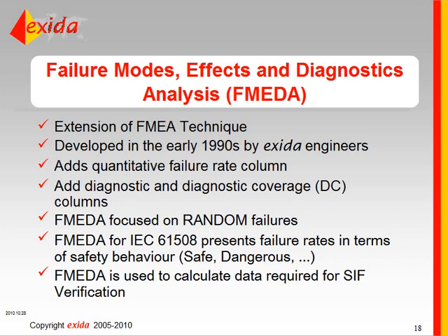It's focused on assuming that the design is correct, the parts are operating within their correct ranges, and there's still an expected failure rate of components even when they're not overstressed and when they're used properly. And those are considered random failures because they occur at random times. It's during the useful life of the component, too. The components have an expected life where they'll hit a wear-out mechanism, and this is the random failures that might occur before that point.